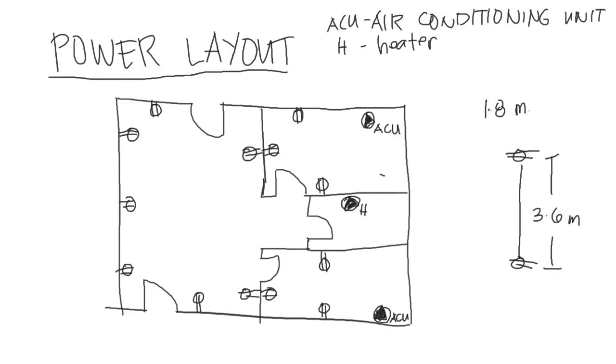Like that. We consider the wall usable, meaning walang nakaharang na furniture or any material sa wall. If there is a furniture, then it is not included in the calculation for the 3.6. And also the door is not included in the 3.6 distance. Okay, so if you're done putting your convenience outlets here, then you are ready for the